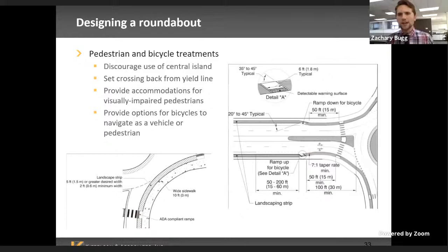In Toronto, you probably got plenty of that. At a roundabout, you don't really have that opportunity. So what you want to do is try and channelize and help pedestrians wayfind their way to the crossing, and shorten the crossing distance. This way, it's a lot easier for someone with a vision impairment to do the wayfinding through the roundabout.